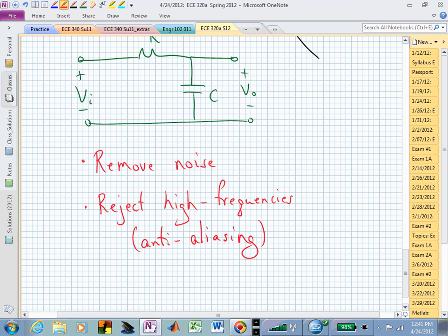So think of your old westerns and the wagon wheels spinning. Sometimes those don't really look like they're going forward. That's sort of this idea of aliasing. Things are looking differently than they actually are because of the way that the system is being sampled. An alias in frequency, you might have a frequency that's actually at 20 hertz, but it gets aliased by the way that you've sampled, and now it's actually appearing like it's 4 hertz, depending on how you've sampled or what you've done. So that's what the aliasing is referring to.